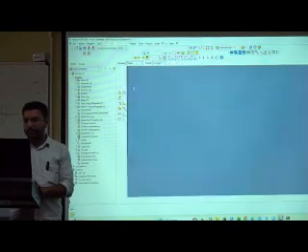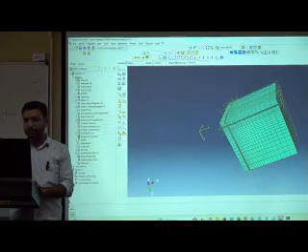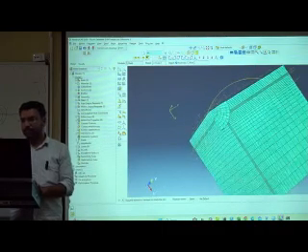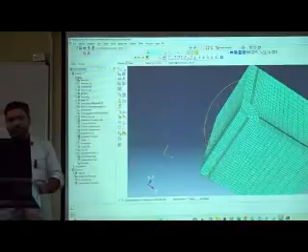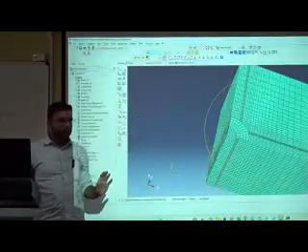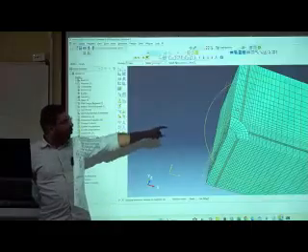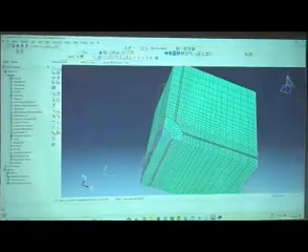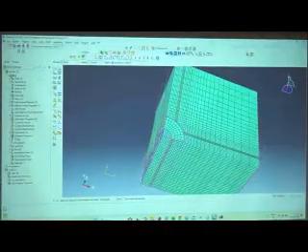After this, this meshing part is there. So see, near the structure, the mesh is finer, and away from the structure, the mesh is coarser. Okay, you can do this with the local seeding. So this is the point you select. Then,